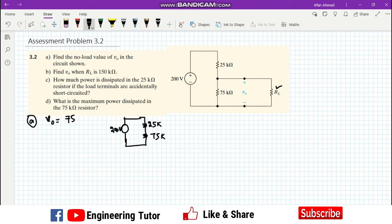To find the voltage here, which is V naught, we will use the voltage divider law. According to the voltage divider law, this is 75k divided by 25k plus 75k multiplied by the total voltage, which is 200 volts. So V naught here is basically 150 volts.